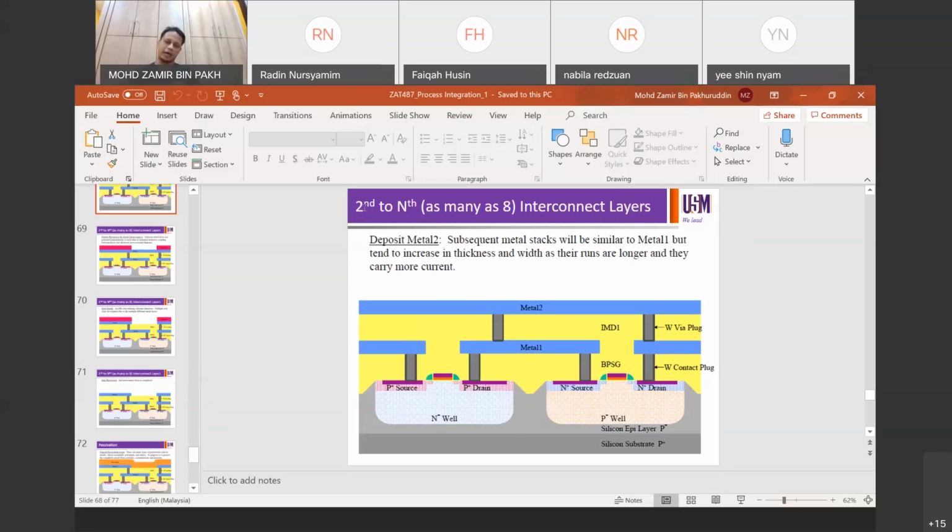So then you're looking at different device architecture. You're looking at, for example, a P-type wafer, then diffuse N-type phosphorus, and then you're going to have anti-reflection coating. You're going to have laser scribing for PERC structure, passivated emitter rear cell contact device architecture, and then you're going to have your top contact silver. You're going to have your rear contact silicon, then done. So that is the whole process integration coverage. For example, if you talk about a silicon solar cell company, the integration varies.